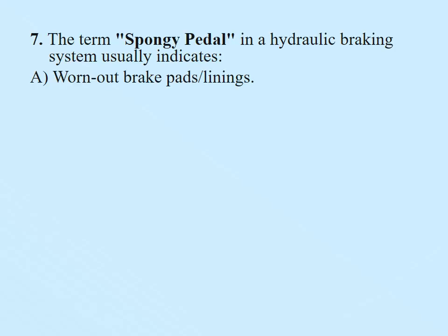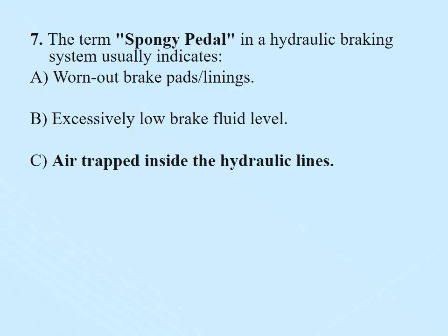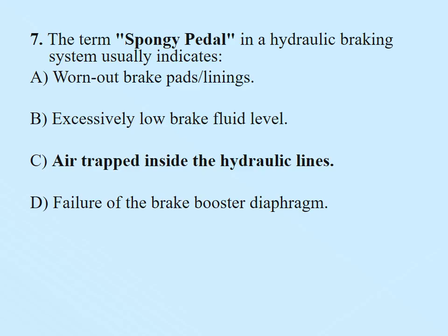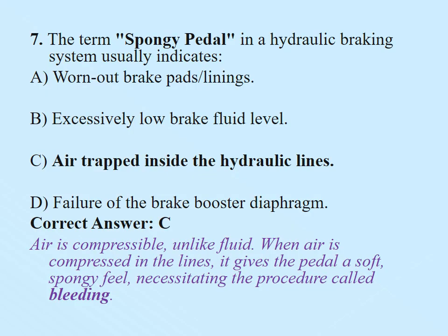Question number 7. The term sponge pedal in a hydraulic braking system usually indicates: A, worn-out brake pads and linings; B, excessively low brake fluid level; C, air trapped inside the hydraulic lines; D, failure of the brake booster diaphragm. Correct answer is C. Air trapped inside the hydraulic lines. Air is compressible, unlike fluid. When air is compressed in the line, it gives the pedal a soft, spongy feel, necessitating the procedure called bleeding.